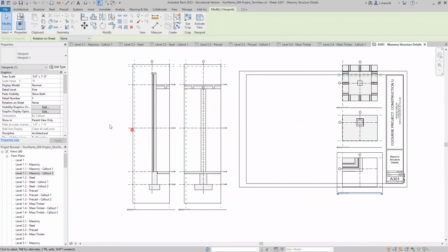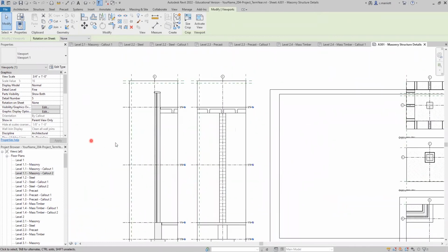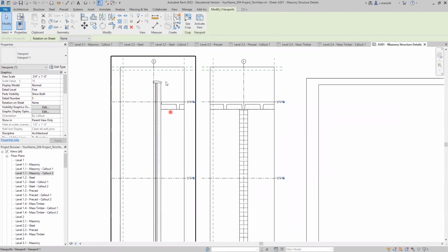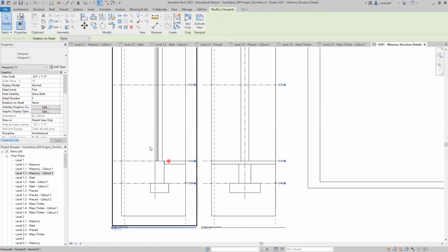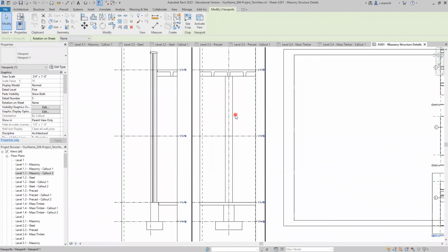Now, the big picture is this: when you're doing wall sections, most of the notations are going to happen around where you have joints between different planes. So there'll be a lot of notes in this region up here, and there will also be a bunch of them on this lower portion. But we have a 2-story space in this case, and so there's a big chunk of the wall section that we don't really need to show, and we'll use a kind of cut line to indicate that. Same thing goes for this one.